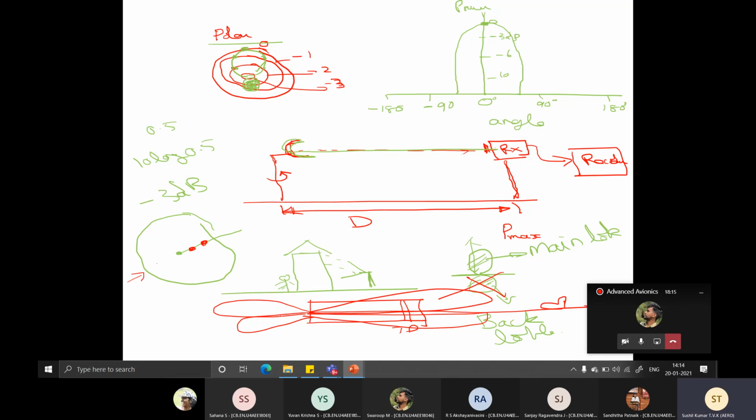You use the instrument landing system only when the weather is bad, this fellow might mistake this to be the approach, and the aircraft can even land on this back lobe, which means he's going to get into problems. Getting it? So depending on your application, this back lobe has to be minimum. Whenever you have directional applications, you would like to have minimum back lobes. It's again same like your car headlight. You want all the light to go forward. You don't want anything to come into the passenger compartment. Similar to that, directional antennas should have minimum back lobes.